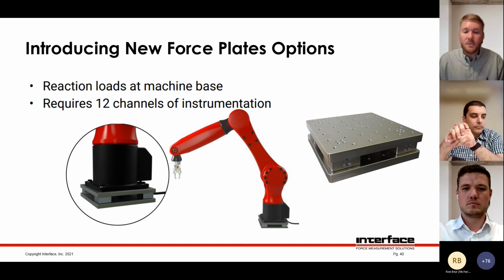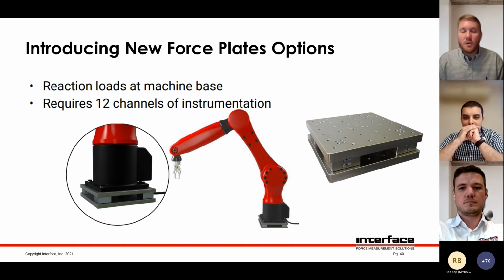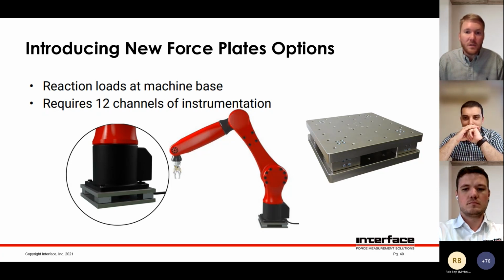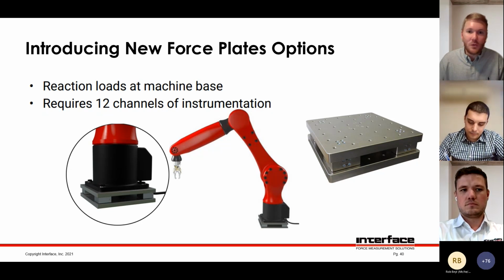And a lot of times these will be calibrated once they're installed, so an in situ calibration a lot of times is going to be best. And sometimes that's not possible. It's easy to calibrate a low profile load cell using one of our hydraulic presses, something like this. We may need to partner to figure out exactly how to apply the loads to a force plate like this.